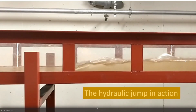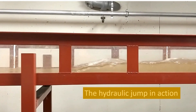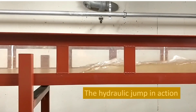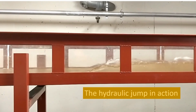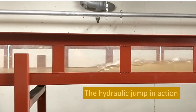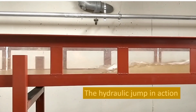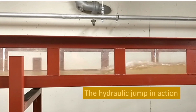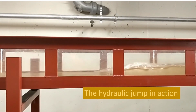So here's the hydraulic jump in action. You'll see that it's actually moving very slightly downstream. This is because it's not reached a steady state yet, but we've just been adjusting the downstream weir. At the point where it's all reached steady state, everything stops moving around.